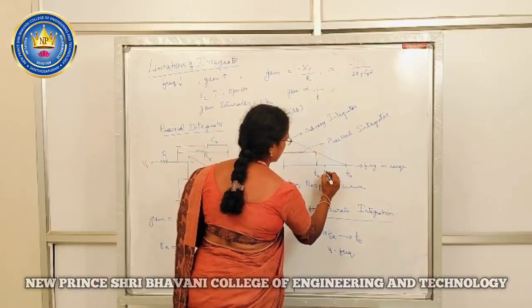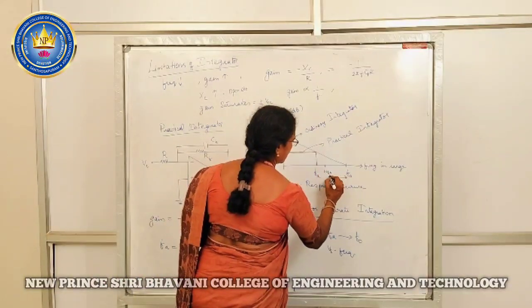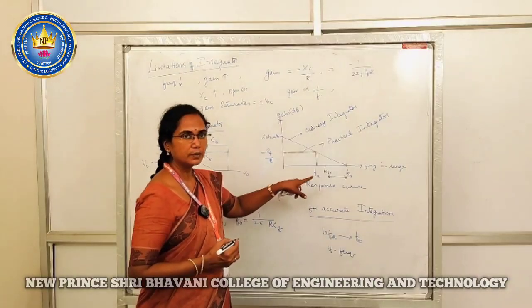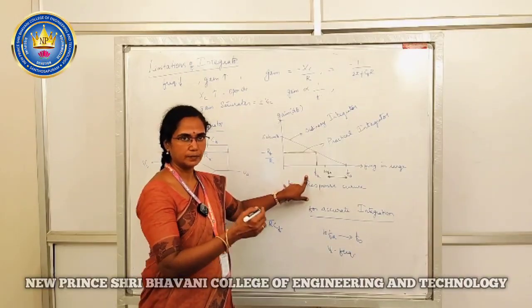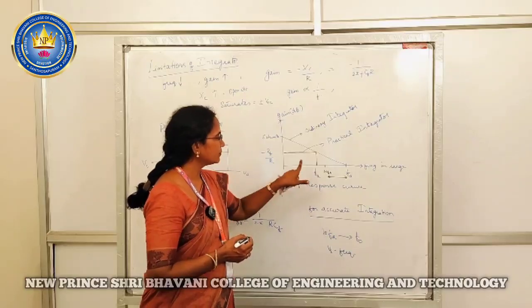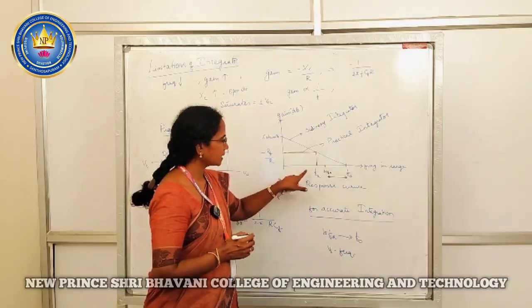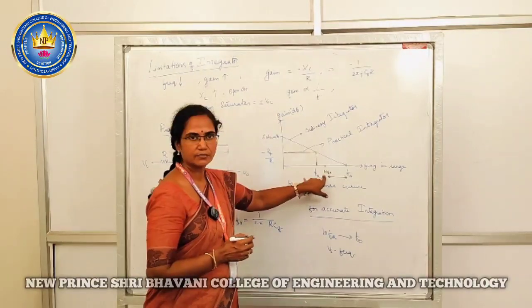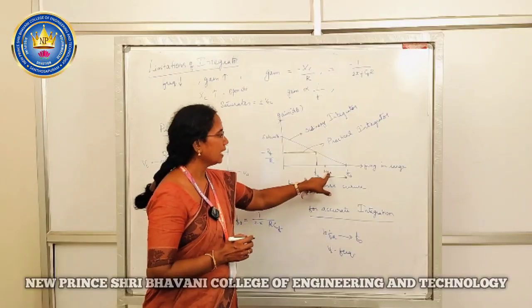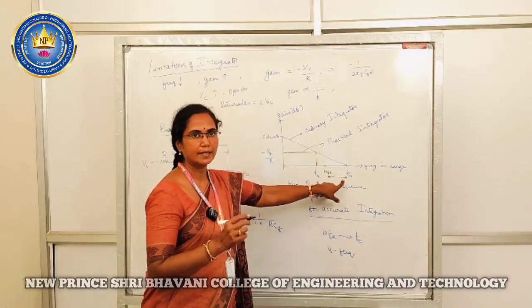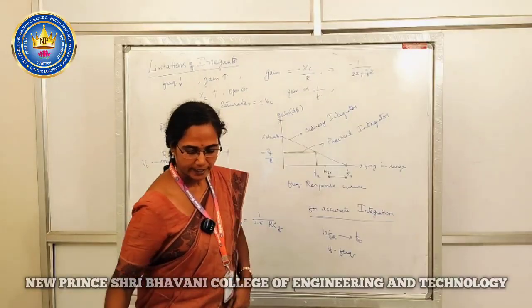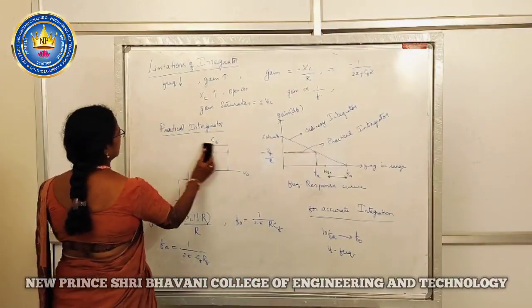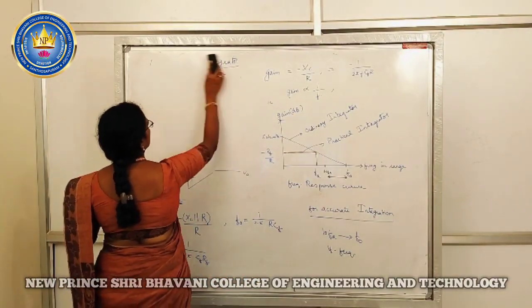This is the range of input signal frequencies for which the integration result is 100%. Before Fa there is 0% integration; from Fa to 10 times Fa it is 50% integration. Only after this will you have 100% accurate integration. Next we will see the input-output waveforms of the integrator.